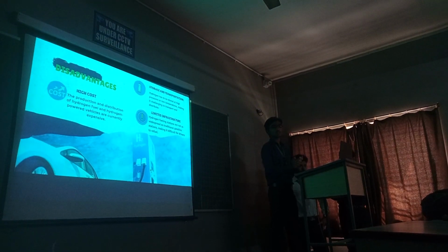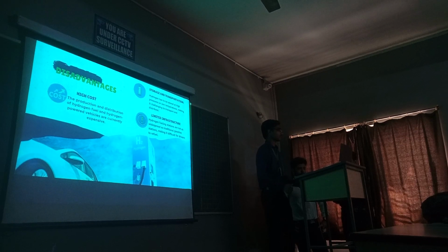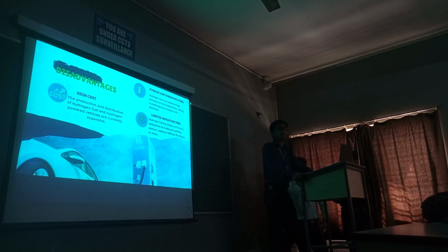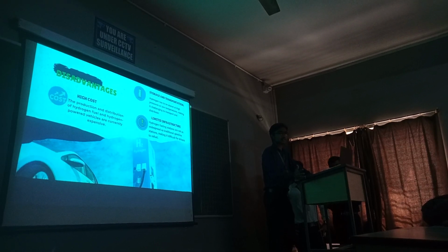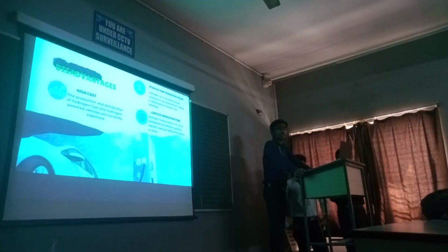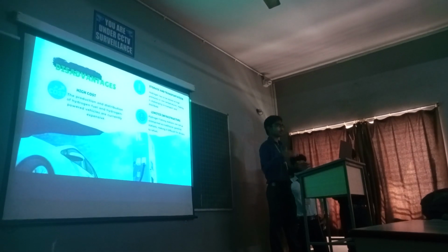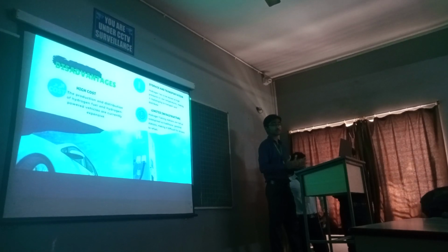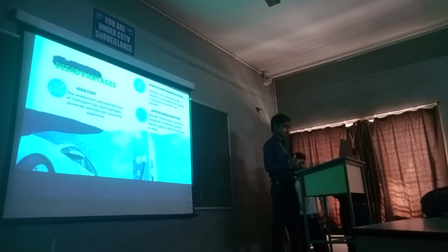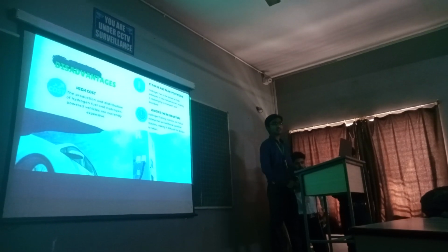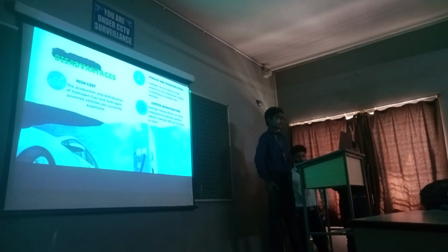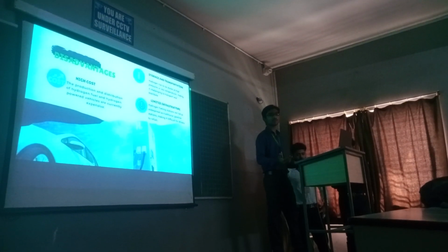In spite of having all these advantages, there are some disadvantages also. First of all, high cost. The production and distribution of fuel cell engines and hydrogen powered vehicles are very costly now. Then secondly, storage and transportation. Hydrogen has to be stored at very low temperature and high pressure, which makes it very difficult to transport and store. Then limited infrastructure. Hydrogen refueling stations are not as widespread as normal petroleum stations, which makes it difficult for drivers to refuel their cars.